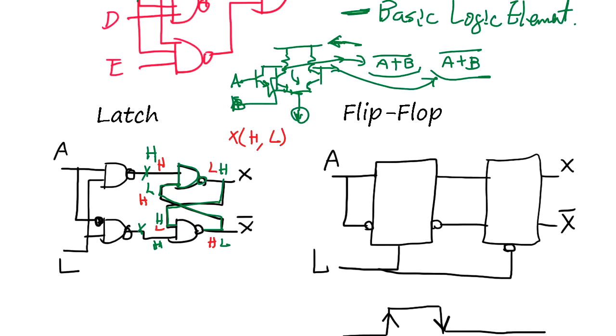Then how do you control that? You have a control gate, meaning latch signal. When latch signal is high, then the A goes through, but A is inverted here, so it's going to give either high low or low high, and that determines the state of the latch. Once it's determined, you bring this low, then both become high, and the latch state stays the same.